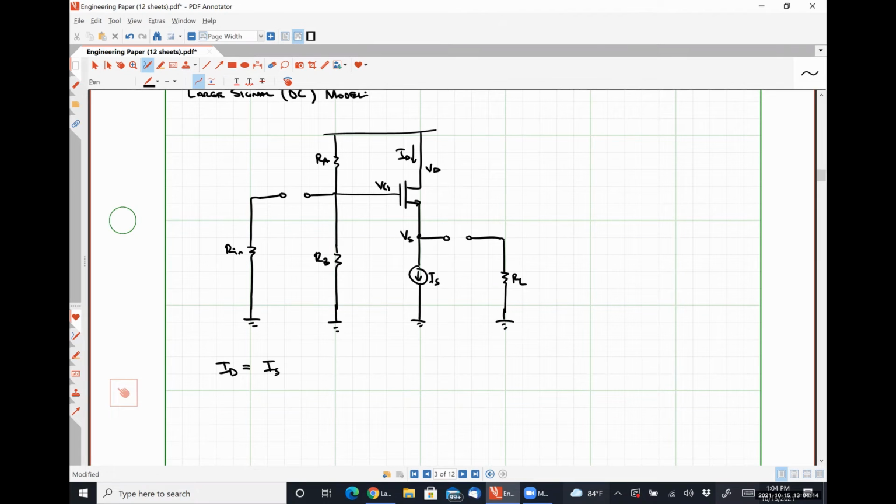So when we bias this guy with a current source, we're forcing the drain current to have some fixed value, which is then going to force our source voltage to be at some point where effectively it causes our source voltage to shift around until the VGS across our transistor is what it needs to be to maintain that source current, right? So it's going to move that source voltage up and down, which in turn translates to a voltage drop across our output resistor when we are looking at our small signal model, okay?